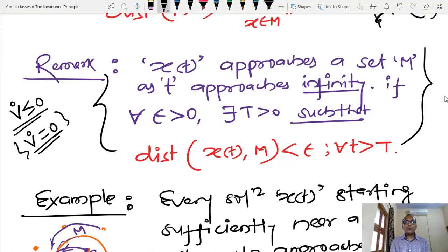Okay, now what we are telling is that whenever we are inside this particular set, whenever we start anywhere, is it possible to converge to this particular set or not? That kind of condition is basically given by V dot less than or equal to 0. So if V dot is less than or equal to 0, then I can guarantee that if I start anywhere, finally I will converge to this set. Does anyone have confusion on this point? Then please let me know.